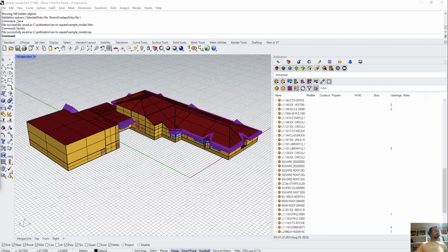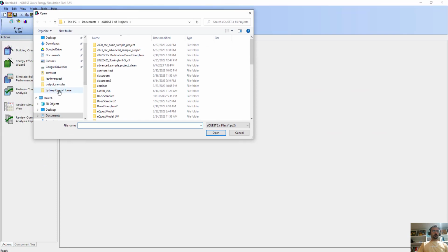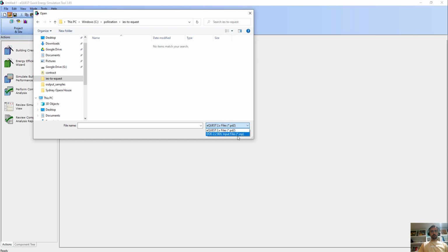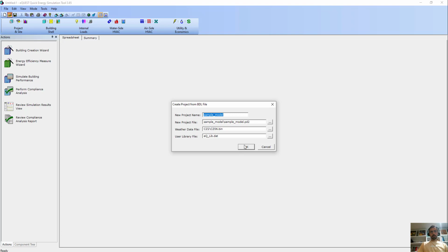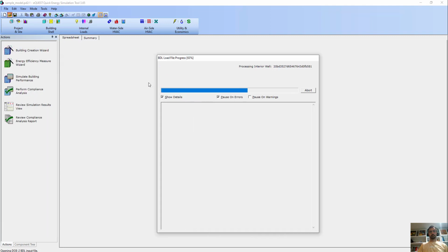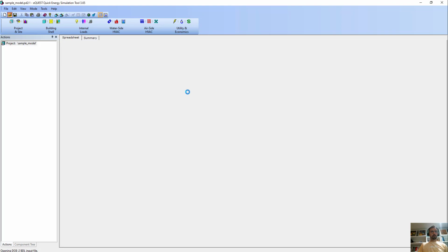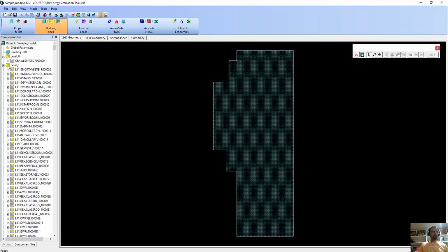So now if I go to eQuest, I can go open, go to that folder that I just created, change this to INP. I think it stands for input. I might be wrong. And then select OK. And it should start importing the model. It'll probably show up on the other. Here you go. So here, this goes, no errors, 6 warnings that we can most likely ignore.